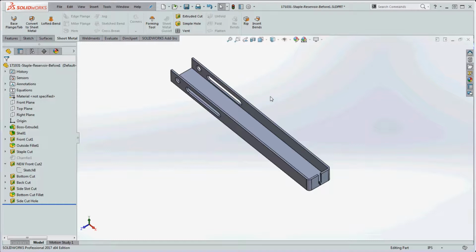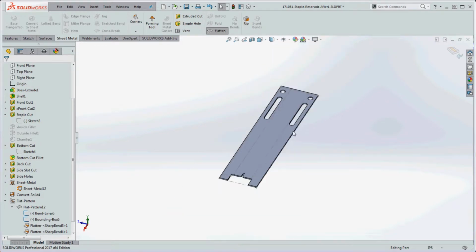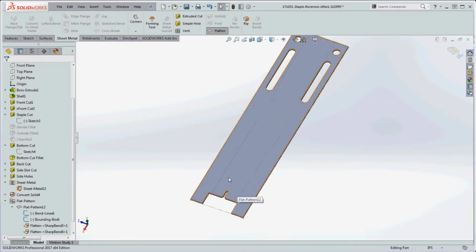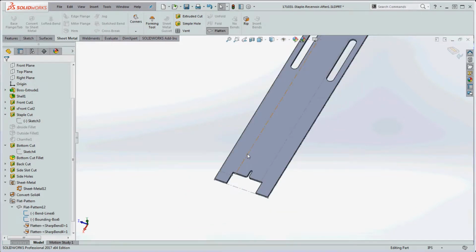to do that. But essentially what you're going to do ultimately is you're going to get a flat pattern like this. And the sheet metal operator is going to go ahead and cut this out with all the holes and stuff like that in there. And you can see that we have lines in here that show where the bend lines are going to be. So it's going to put that in some sort of jig. It's going to bend it along that bend line at a specific radius.